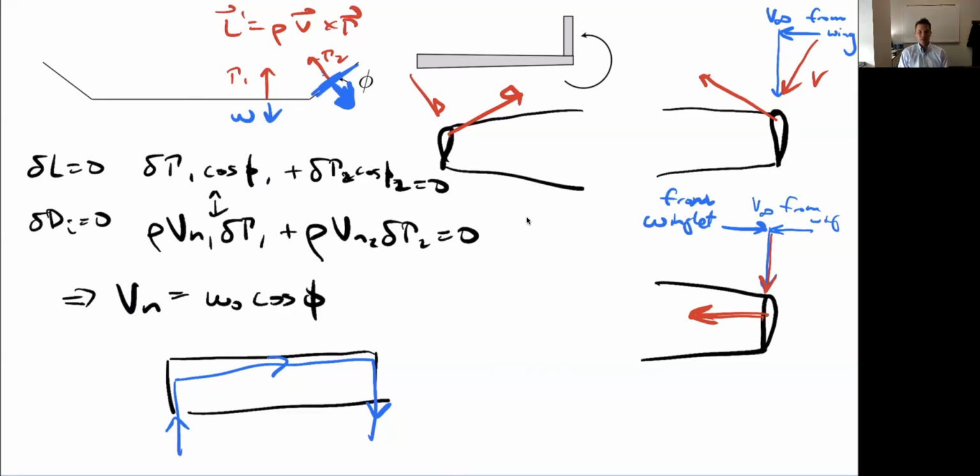So I know this takes a little bit to visualize. You might have to sit down with this and try this, but for this normal loading here, right, like this vortex here, we rotated it, and now we're looking at a sideways view. So when I rotated it, it's going from out to in and out of the page here. So that's like this direction here. So the winglet, as shown, is now inducing an upwash on the wing. So that's going to reduce the induced drag on the wing.